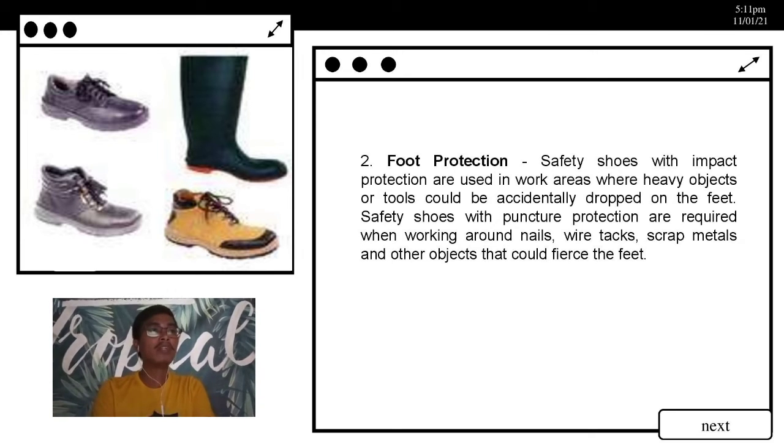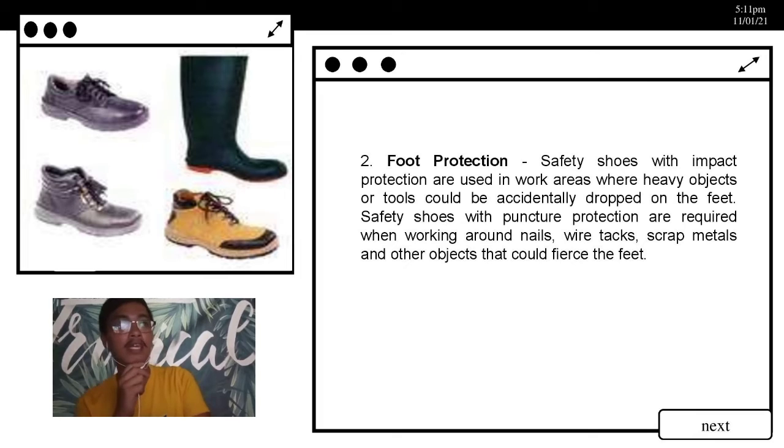Next is the white rectangle with the orange Greek letter omega, which indicates electric shock protective footwear. This is intended for industrial work environments where accidental contact with live electrical conductors can occur. The warning is that electrical shock resistance deteriorates with wear and in a wet environment.